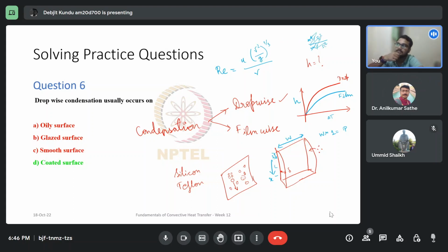So here the length scale, for the Reynolds number, what we know, the usual thing is UL by nu, right? Since there is no characteristic length scale associated with the problem, we will find another length scale which comes from the properties. So here nu is what? It is a property of the fluid, and g is the acceleration due to gravity. But if we manipulate this mathematically, nu square by g to the power 1/3 gives the dimensions of length. So we can incorporate this as well in order to find out the Reynolds number.